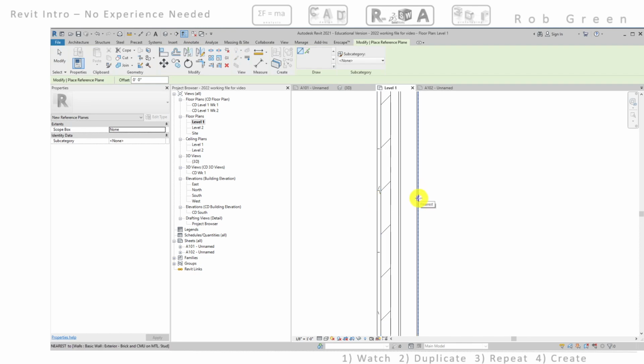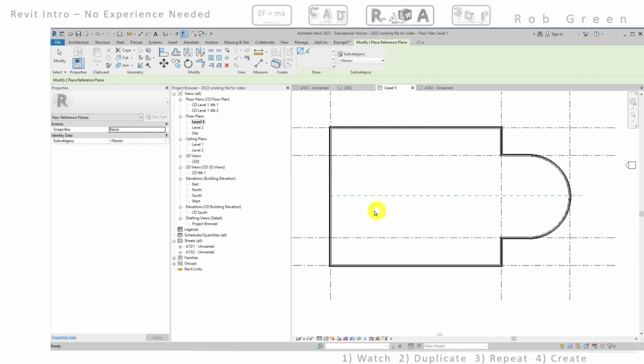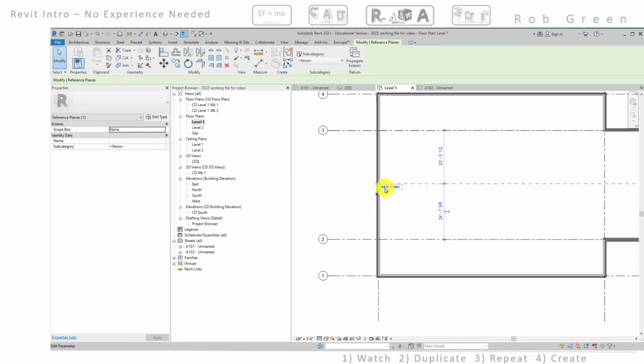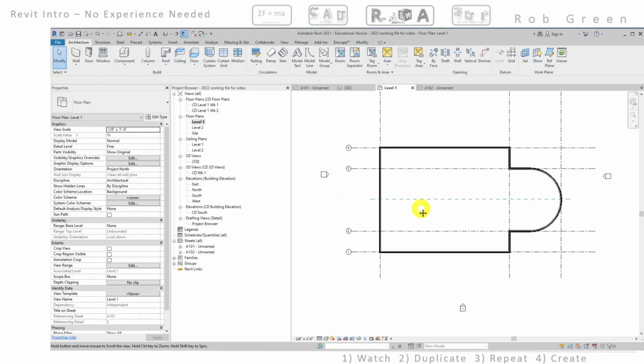And I got to tell you, when I see something I don't expect, the first thing I'm going to do with that is I'm going to zoom in. So there's my midpoint snap, and then zoom back out and draw this line out past the building, something like the textbook shows us to do. The textbook also tells us that we have some grips, and I can drag this line a little bit longer. Great, done.